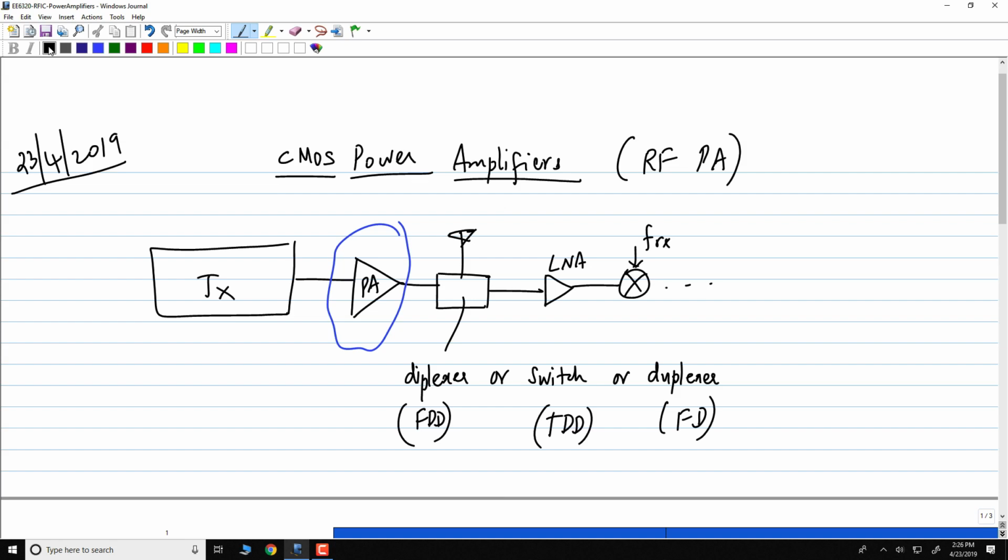What is the best possible receive sensitivity that you can achieve? That is known. Now you work backwards, figuring out the approximate attenuation you get over that range. You can automatically set the total transmit power that you need to achieve.